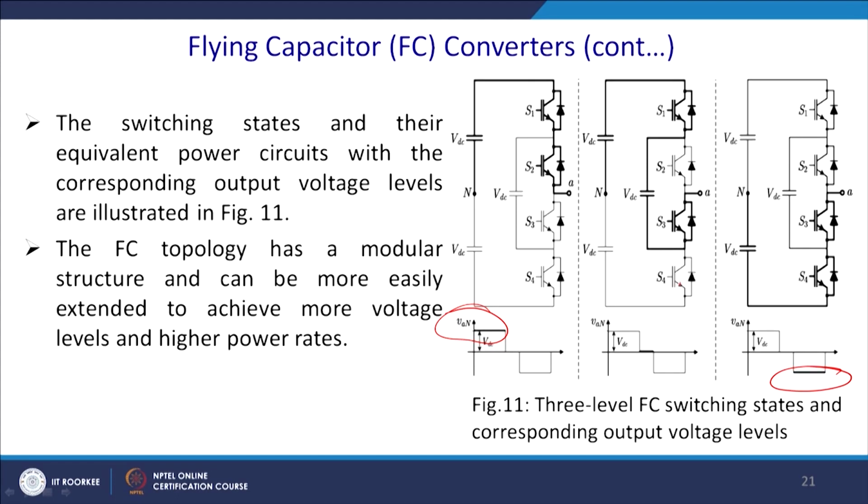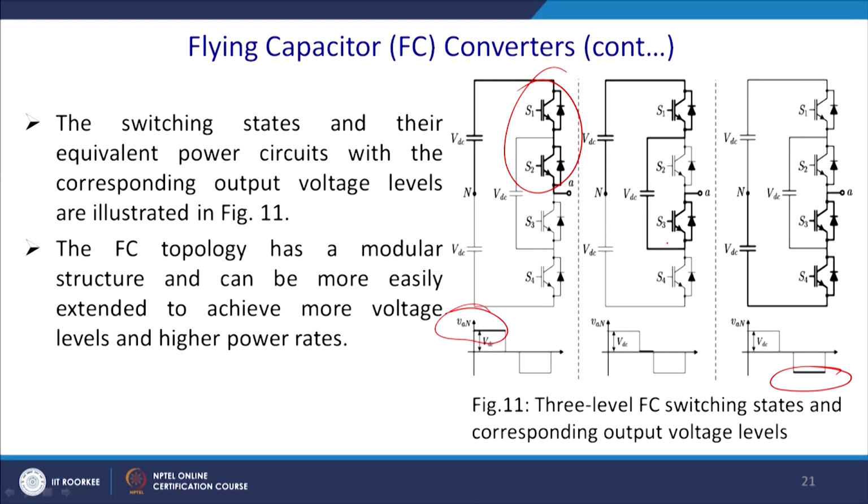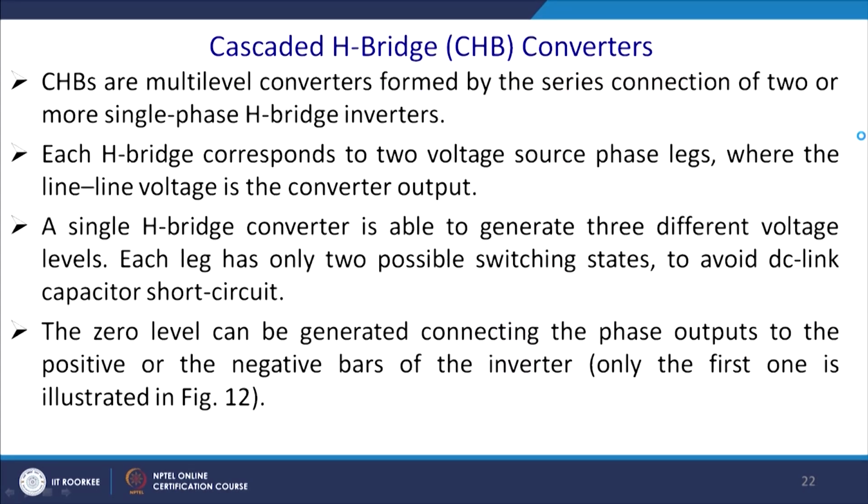different ways. That is also essential to reduce the switching losses, and the state transition will occur with the minimum switching. If you are in S1 S2, then definitely you will switch to S1 and S3 to get the 0 voltage. If you are in S3 S4, to get the 0 voltage, you should switch on S4 and S2, which also gives you the 0 voltage. So, you can accomplish different stages of the voltage, including 0 voltage, by one change of state.